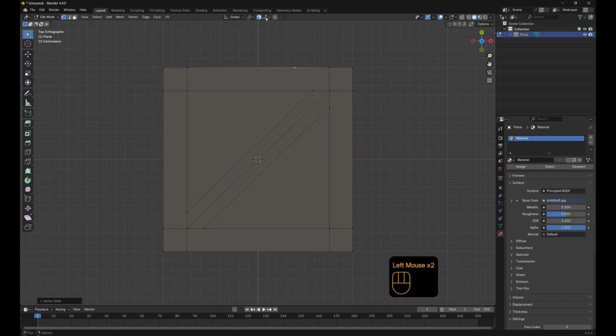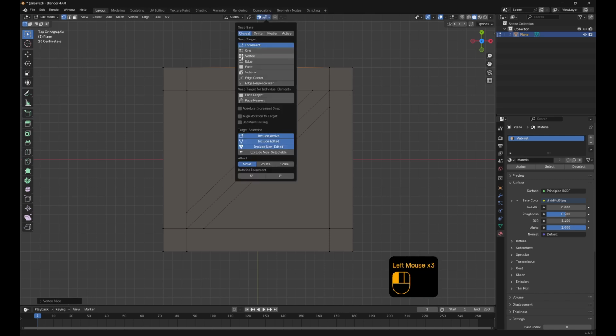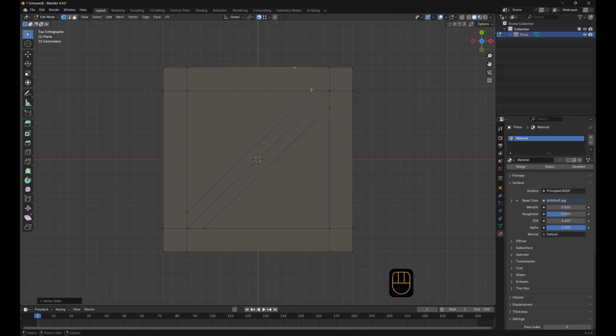If I turn snapping on, come to the menu, and let's align it with a vertex. So this option is how do you want to align what you're snapping, and I want to align a vertex with a vertex. So double G, move it along, you see it's still free until I move my mouse down, and then it snaps to that vertex just there. Thank you, Blender, for putting that on. That's fairly new that you can see that, and doing my first recording like this, it makes it a lot easier to show you guys what I'm trying to showcase. Let's do it for this edge.